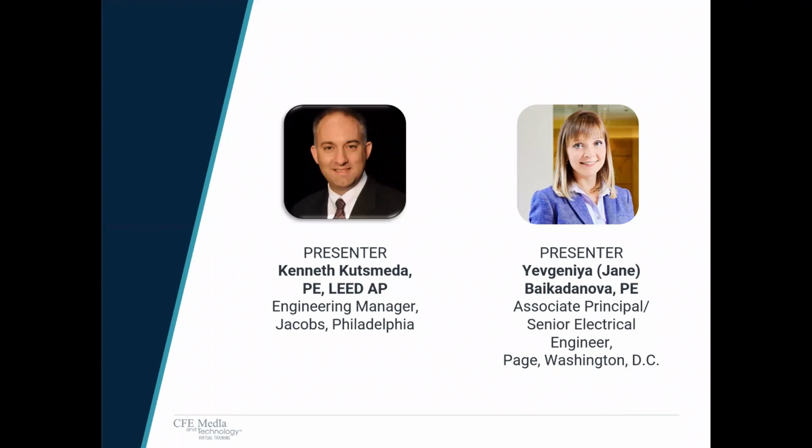All right, got it. Thank you. Ken, I'm going to kick this next question over to you. Should the engineer of record seek to obtain the utility company's fault current to calculate the AIC ratings for the equipment, or should the contractor, because during design, the engineer may not obtain this information for the permit drawings? Can you talk a little bit about that process?